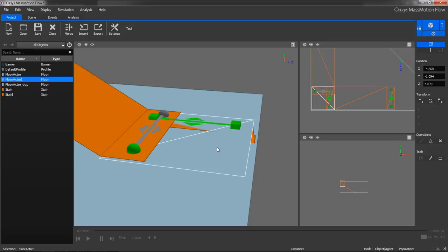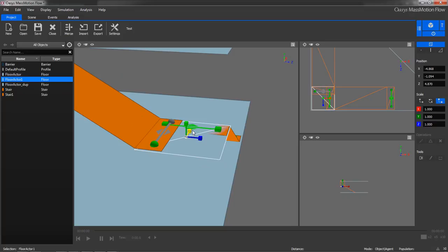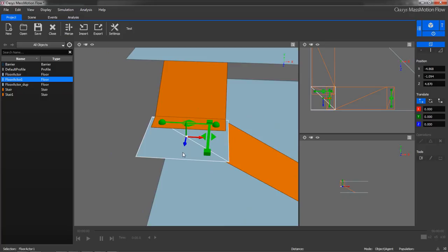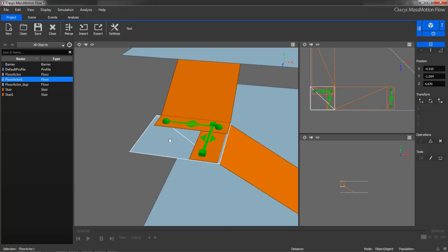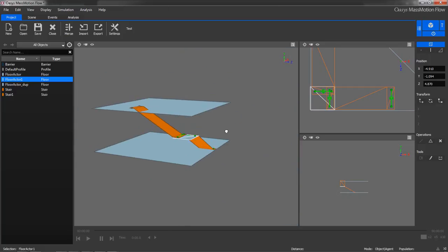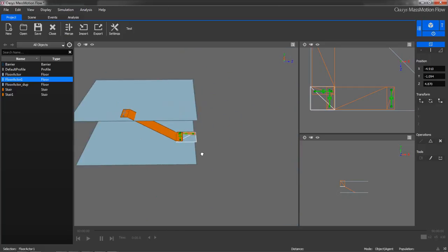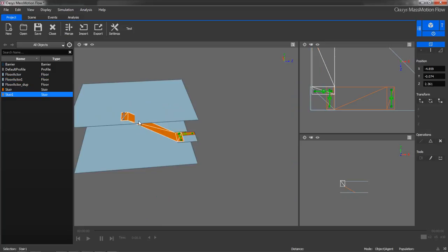It looks like this needs to grow just a little bit in the other axis now, so that we've actually got both of our stairs properly accounted for. And there we go. So now we have 2 stairs with a landing and extending all the way up to the 2nd story. This stair isn't quite positioned properly, so I'll select the vertices, constrain it to that plane, and adjust it into position.